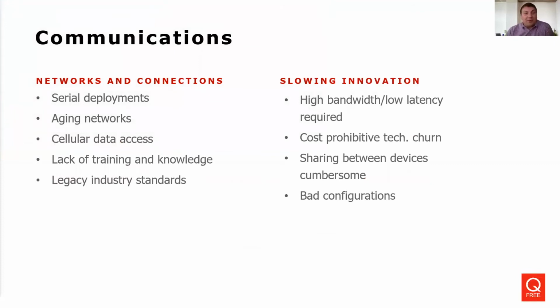Communications is the last one we'll talk about in detail here, and then we'll get into maybe some more fun stuff. But essentially, comm is critical, and IP-based networks with Ethernet started being installed 15, 20 years ago. But the issue with that is a lot of those early systems are old. Also, fiber gets cut by contractors, or if you're doing Ethernet over old serial copper lines, they degrade. Wireless radios get bumped by wind and branches falling. And soon enough, a lot of agencies, especially smaller ones that can barely afford maintenance and things like that, or have to appropriate their funding all to maintenance and roads, their communication's no good. So now we have this great signal system installed, these new controllers out in the field, and you can't actually talk to them. So we're not really gaining the value we need out of that solution.